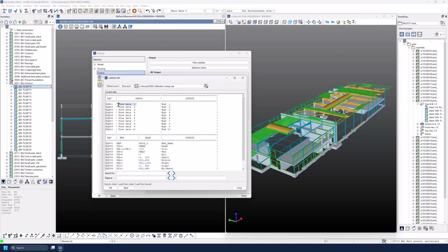So what I will do here, I'll set up a test. So this little test will be key EQD01, and I will say you give me the property of the profile slash for the next piece of information. In this case, it will just be a space, a dash, and another space, slash to go to the next property, and then I'll say tx plus 6, which is the material. So that will be EQD01.